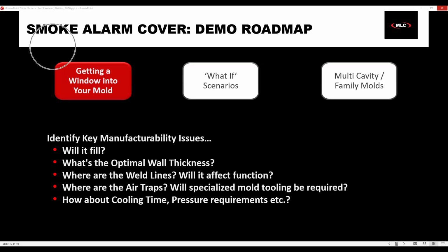And then you also see over here on the left your plastics manager, which is very similar to any other simulation tree that you've used. So again, this is where we can go to set up the study. Now, I am going to walk through the study setup here because we make very little modification to it later on. We just duplicate the studies. So I'm going to talk a little bit about this now.